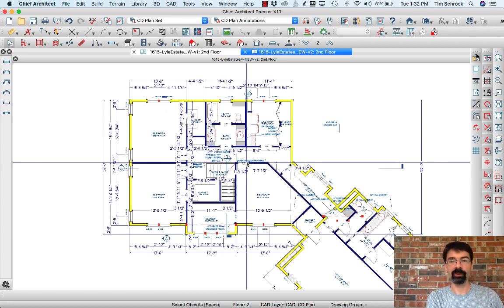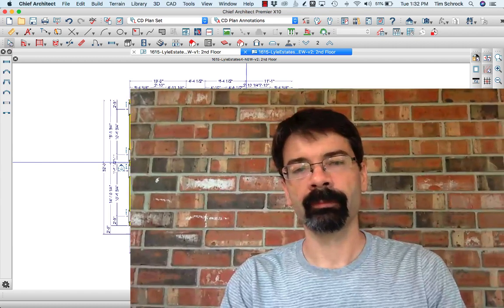So all those objects are in the exact same place in my world on the screen, and that way when my notes and my dimensions come over, I can go back on version 1, copy all the notes and dimensions, etc. onto paste in place onto version 2, because my 0, 0, if you will, is the exact same point because of the way I designed them.